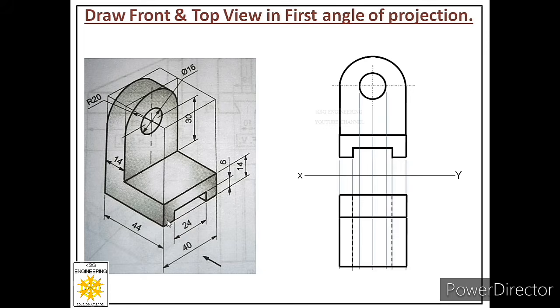This edge of this face is below this edge. So it is hidden behind continuous thick edge. So over here we cannot draw dash medium line. Why? Because if one edge is hidden below other edge, then we will give preference to the visible edge. So we will show visible edge as continuous thick lines on both sides. So we have represented these three hidden faces also.